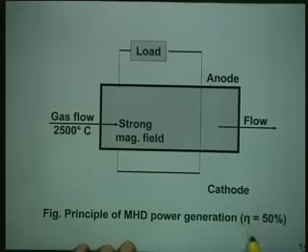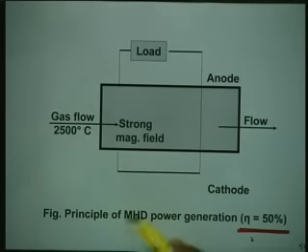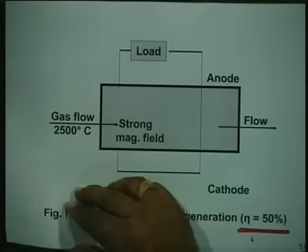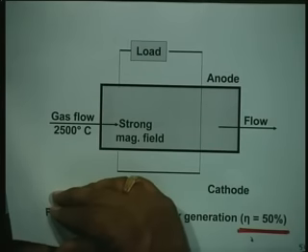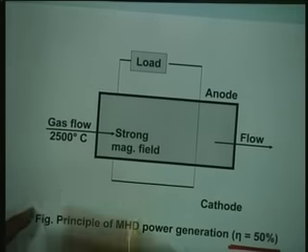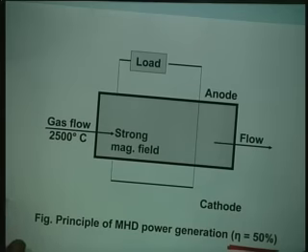Well, efficiency is around 50%, whereas I just now talked about efficiency of thermal power station, which has not crossed 40% anywhere in the world, even with so-called modern technology, superheated steam, reheat turbine. I already explained to you what is reheat turbine. You bring out the steam, pass it through a reheater, again bring it back. Of course, any such thing will have an additional cost. Cost has to be there.